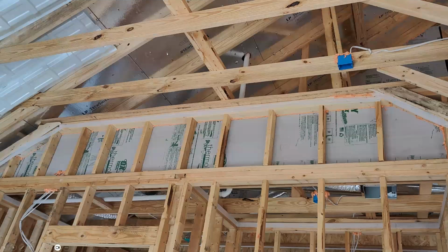Same goes for knee walls, which traditionally are left exposed to hot attics or extremely cold attics. The thought was that the resistance to heat transfer that insulation provides was enough. But through research and studies, it was concluded that this allows hot or cold air to move freely through the insulation, which greatly lowers the effective R-value of that insulation. So an R-13 becomes like a 7, 8, or 9, which then greatly lowers the resistance to heat transfer in and out of the building.